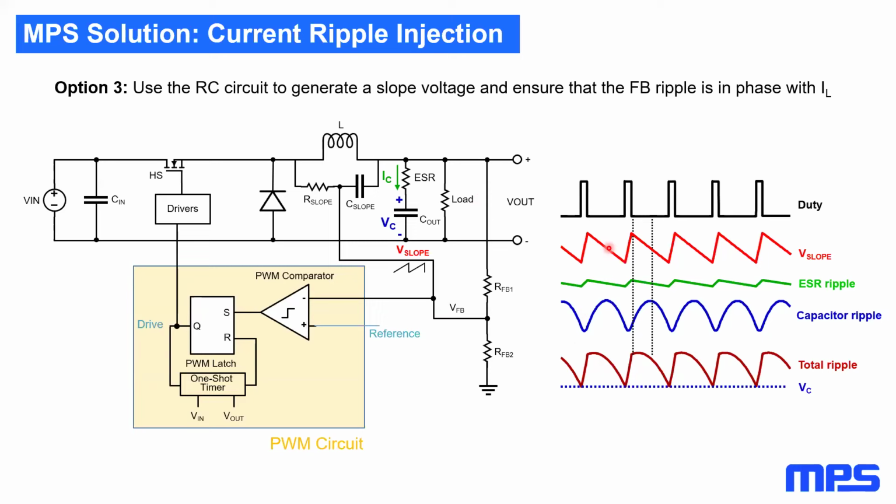This was also an issue for peak current mode control when operating at duty cycles above around 50 or 60%, where any variations or any noise can lead to disarray in the control circuitry and generate instability. So the way that we avoid this is by adding this slope voltage to the feedback and maintaining this periodicity dependent on the inductor current.